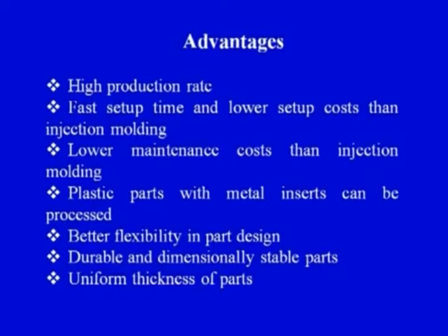The advantages are very well mentioned on your screen, you can have an idea. First is high production rate. So the production rate is high in case of transfer molding. It can be automated also. An automated process can further improve the production rate. Fast setup time and lower setup cost than injection molding.